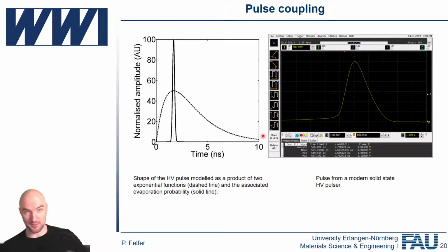So in voltage atom probe, what we have is a high voltage pulse that we couple into a specimen via some electrically impedance matched line. In modern atom probes, it's usually just a 50 ohm line. In old atom probes, it used to be 75 ohm. You don't have to worry about why one or the other. But anyway, it just needs to be kind of like a data line where you have high frequency communication.